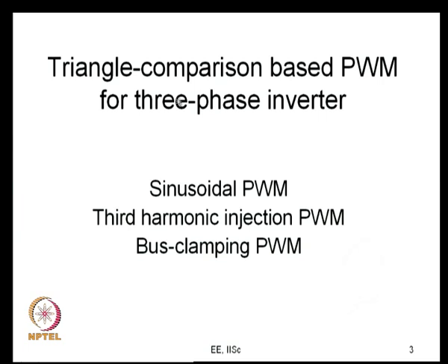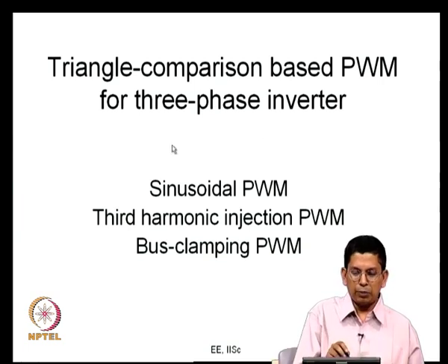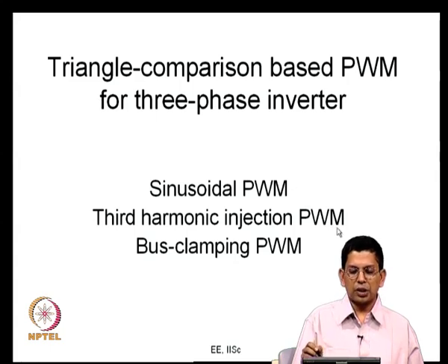As part of this triangle comparison based PWM, we have been looking at the 3 phase inverter. Earlier, we looked at sinusoidal PWM for both single phase as well as 3 phase inverters, and we also looked at third harmonic injection and bus clamping PWM. I can say that sinusoidal PWM, third harmonic injection and bus clamping PWM are all specific cases of triangle comparison based PWM.